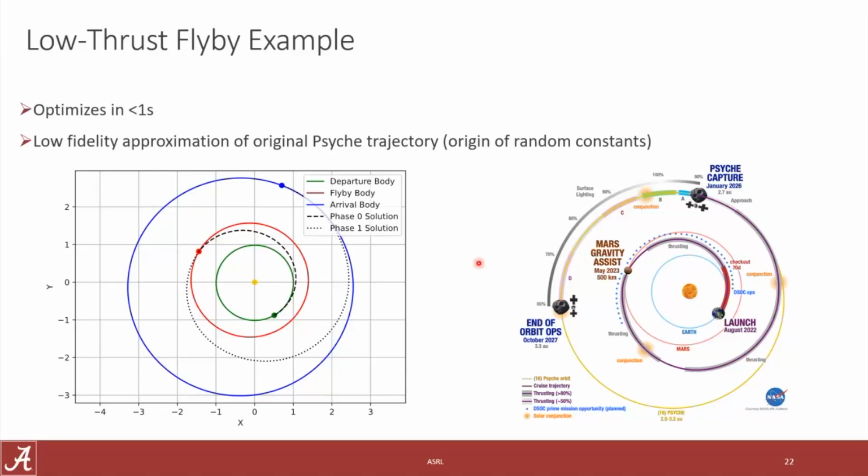Yeah, each configuration of that potential mission makes for a great optimal control problem, but appending them all into one massive optimal control problem is maybe not the best approach. But because it's programmatic, you could use a Lambert solver to configure initial guesses to each of those bodies, and then loop through: here are my initial guesses for Earth to Mars to Psyche versus Earth to Venus to Earth, and programmatically approach that, forming different OCPs. Something like that.